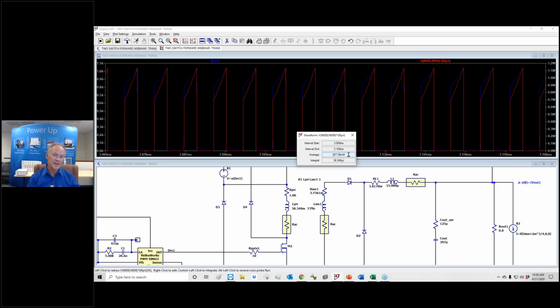So if you're only doing DC calculation on your transformer, this is the number that you got. So you go in carefully and you extract the RMS, and then you do I squared R times the DC resistance. That's the number you're going to pull out. You can say, hey, that looks like a pretty good design. It's a 200 watt converter and there's only 300 milliwatts in the windings.